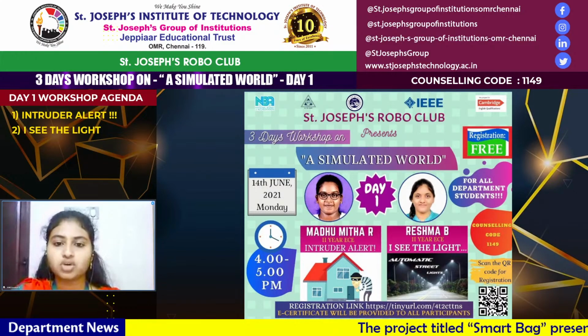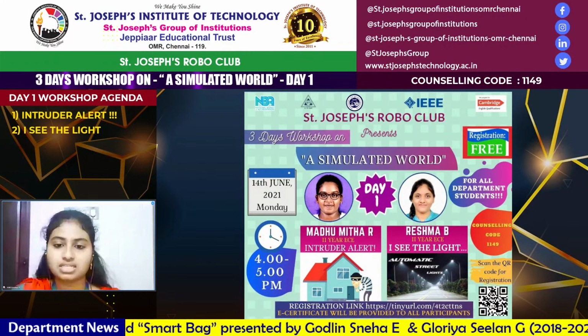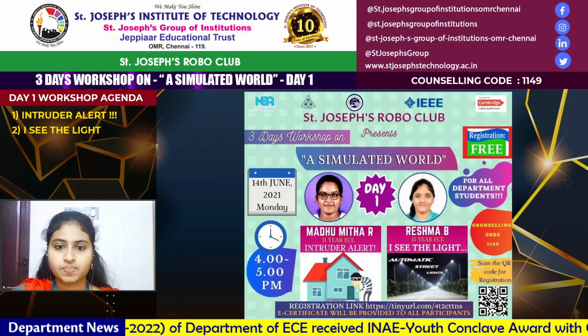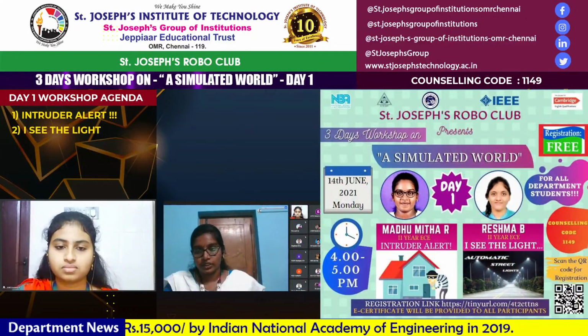Now, these questions are for Ms. Madhumita. First question for you is, why are you using PIR sensor? Can we use other sensors too? Yes, instead of using the PIR sensor, you can use the IR sensor in this place. But like I said before, the IR sensor can only detect the object present in front. The PIR sensor can also detect the motion of the object. So that's one advantage of using the PIR sensor.